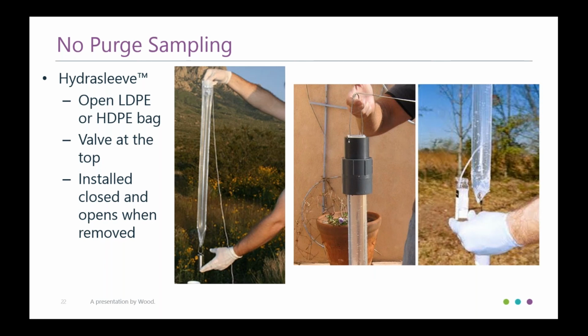I have this installed at one of my sites that is a long-term monitoring site because it has a very fine particulate, and anytime you pump it, it just gets stirred up and floats, and it won't settle out again. So we set these after each one has 15 months out, and there's less disturbance as we pull them out. And this is a site that I need to collect for metals. So this is appropriate for, again, all sample types because it doesn't require passive diffusion, which is the next one. And these also come in HDPE, so you can use them for PFAS.